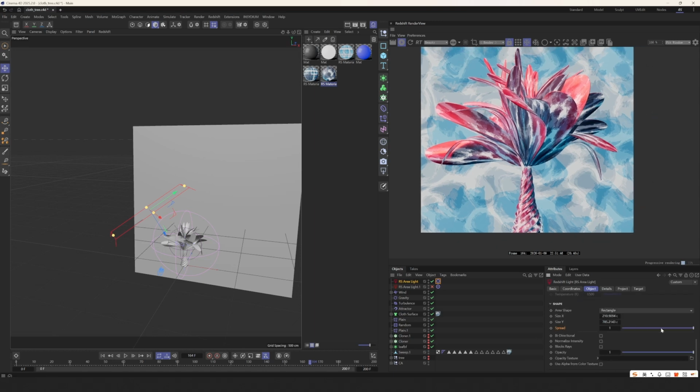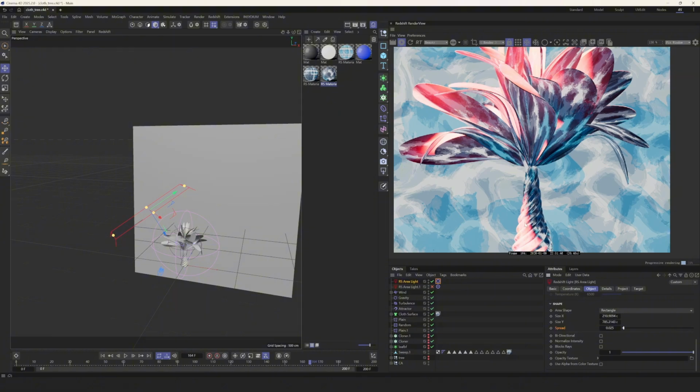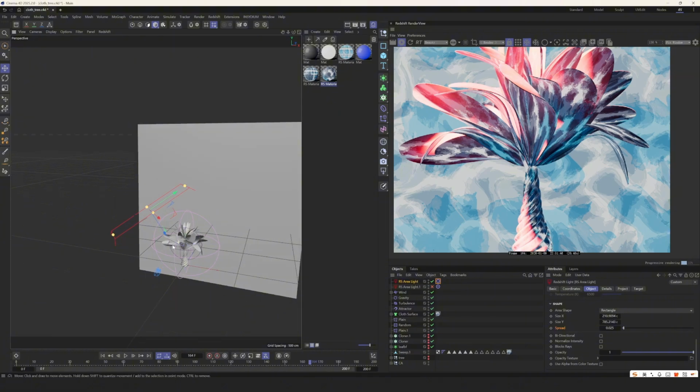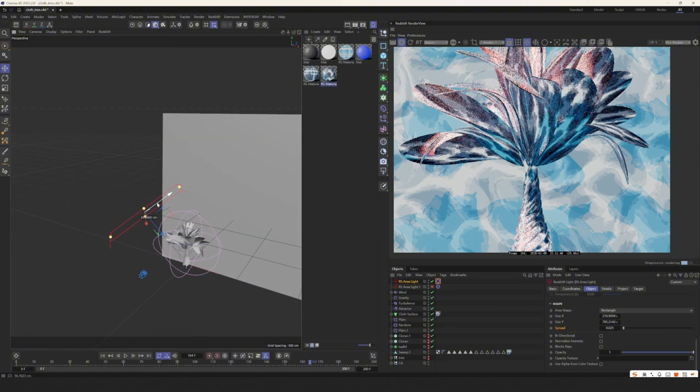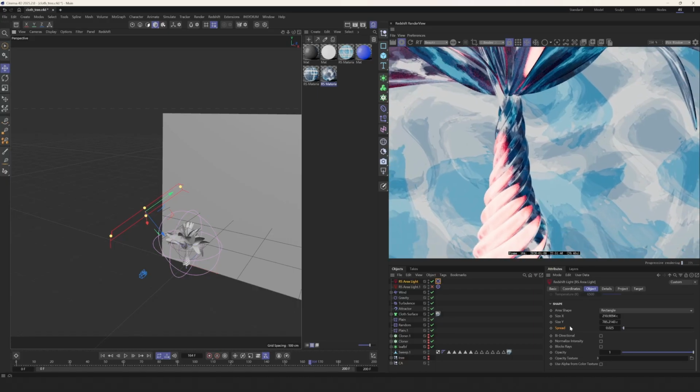The difference is that there is a diffusion value. If we pull the diffusion value very low, it will form a cartoon-like rendering, hiding a transition, the interface between light and dark. You can adjust the position. The light is scattered. Okay, you can also adjust it here by the diffusion value to adjust the transition softness.